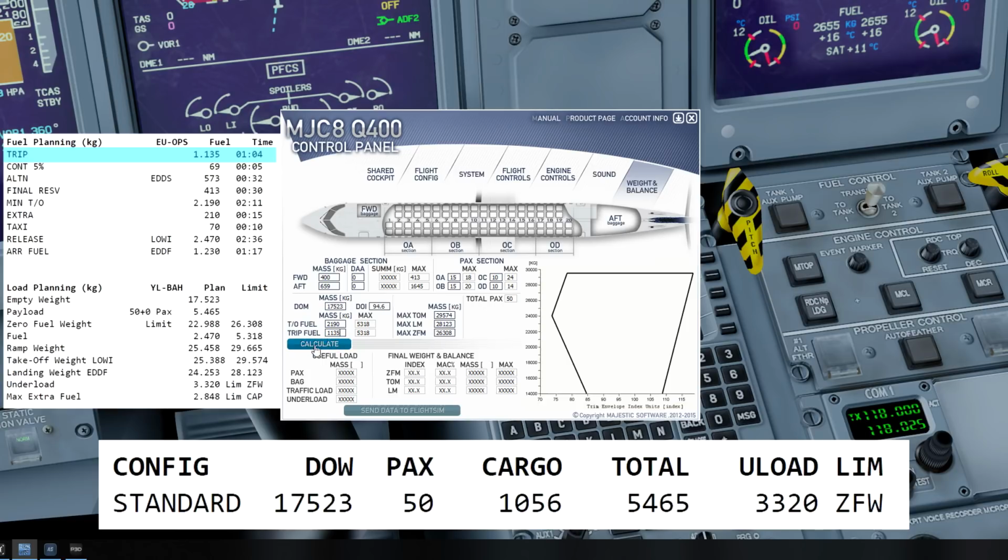Now, what you want to do is click the calculate button, and as you can see, the graph has now displayed some information. If there's anything red in this area, you know that there's something wrong, and if you don't see these boxes within this so-called flight envelope, then there's something wrong as well. That's because it's a pretty weird aircraft in terms of balance. It's really possible that the balance is incorrect. So you really want to make sure that you're entering the right data.